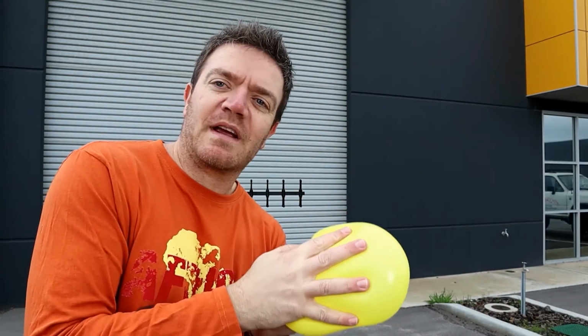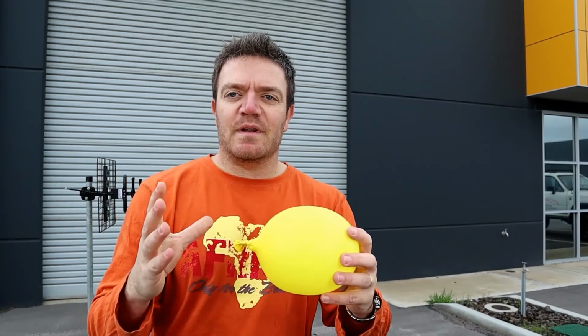Now, as you can imagine, the more you squash, the narrower it would become. So it becomes very pointy, like a laser beam. That's when the Yagis get longer and longer and longer. That has its benefit in certain applications, as I mentioned with my beast in my previous video. But in general applications, something about 11-14 dBi gain is quite useful. Then you still have a reasonable beam width. It doesn't get overly complicated. When you get to 18 dBi, it gets quite narrow. If you know exactly where you are pointing and you are willing to get that absolutely pinpoint, and wind movement doesn't bother you, fine, that'll work well.